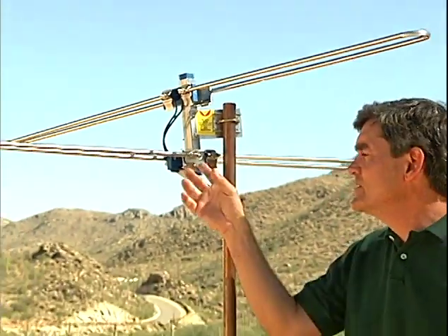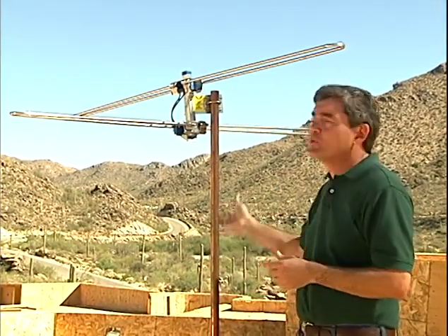Omnidirectional antennas such as this should only be used in areas of flat terrain, void of any tall structures that would cause a problem with reflected or multipath signals, and where the signal strength of the desired channels is adequate. Now, directional antennas fall into two categories: bidirectional and unidirectional.